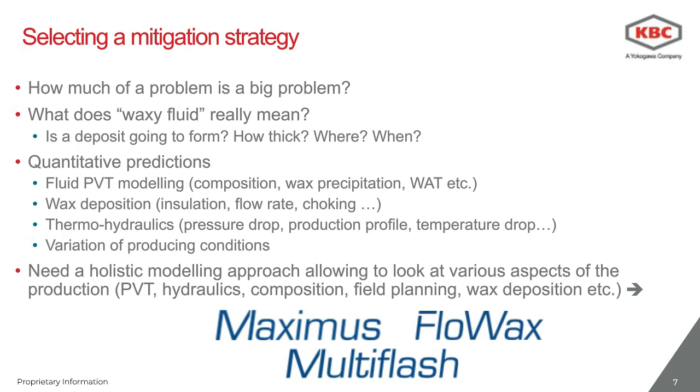Is wax going to be depositing along the pipeline? Where and how much is this going to be affected by the plant itself, by the amount of insulation, by the flow rates, the choke opening, and so on.